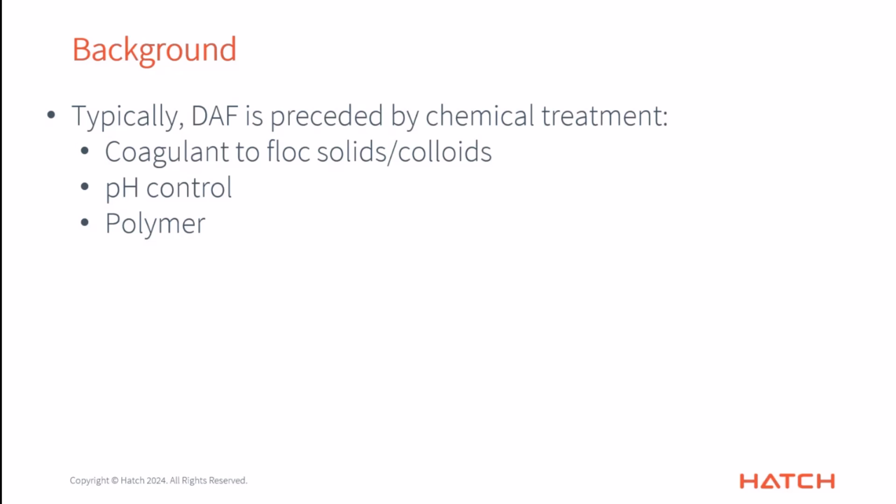And then also typically you're adding a polymer to assist with and improve the attachment of the solids to those bubbles and get the maximum amount of the solids being captured and taken up to the surface of the DAF unit.